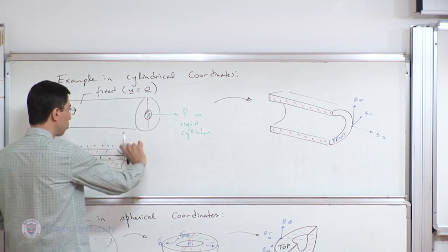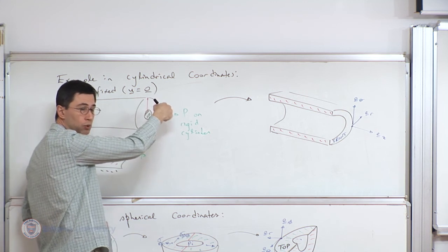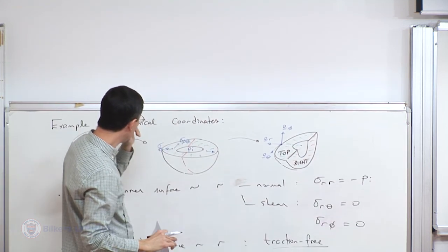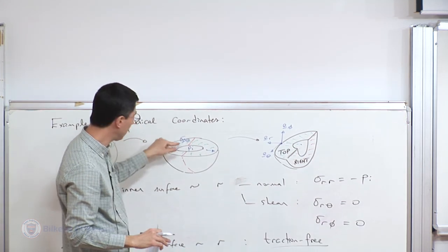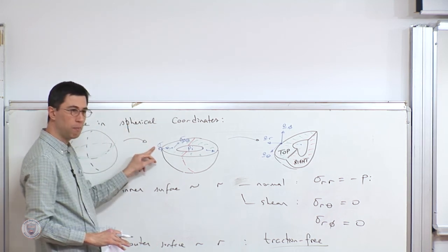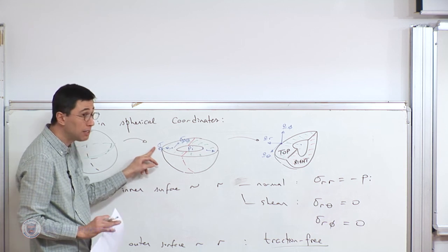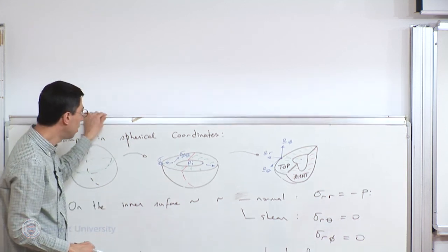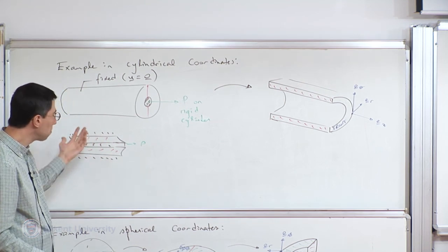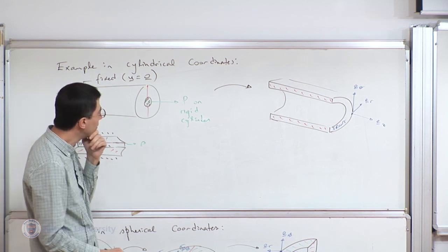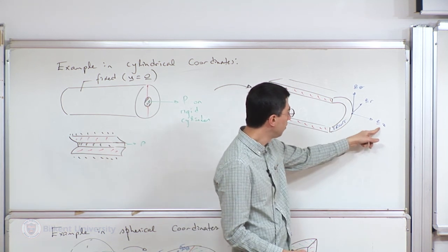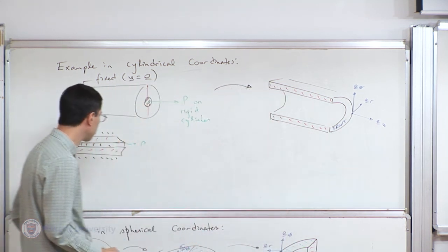Theta, because I'm not trying to torque this thing. If I try to torque it, theta would also be non-zero, but it's zero. So you see, actually, he said that. It's interesting because in this problem, if I'm not torquing it, this component is for sure zero, but it was not clear whether this component of the stress was zero, right? It might not have been, but it is. So the two components are zero. You only have to worry about the axial component.